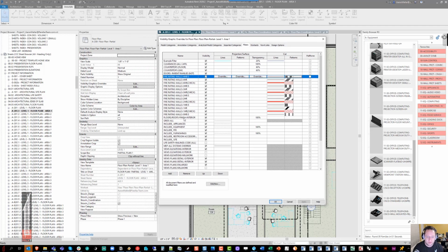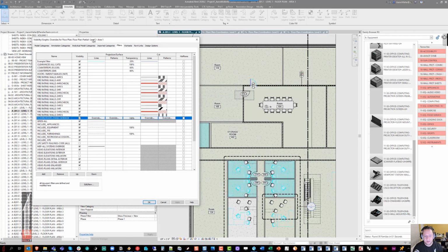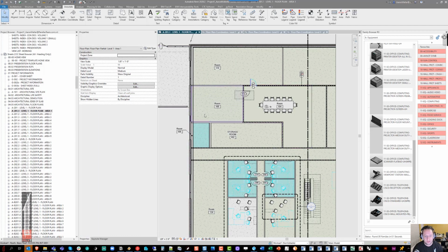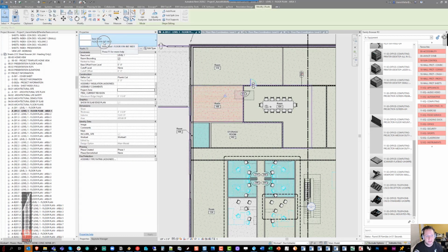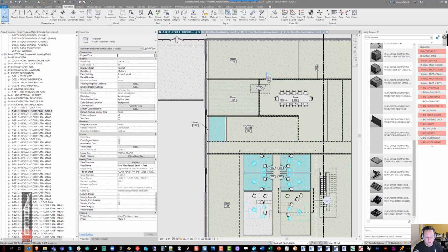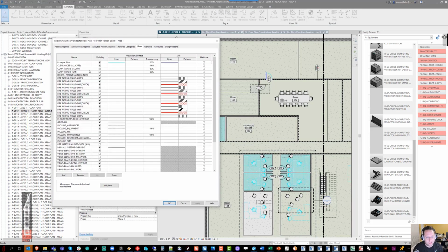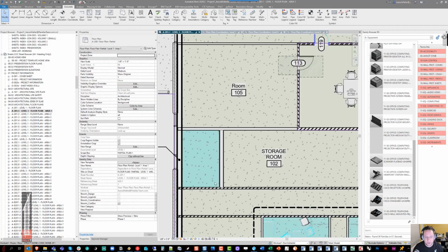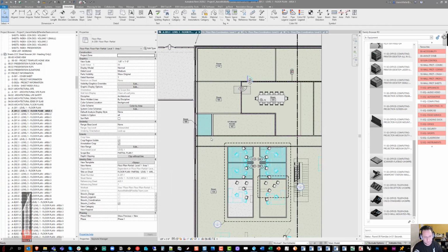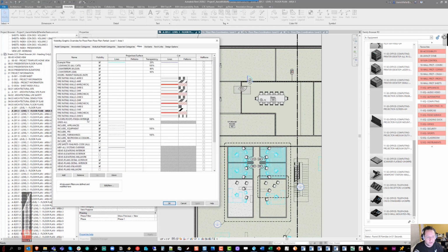Very important filter follows the fire rating, and that is floors and roofs finishes on the interior. This filter is looking for the letters FIN and INT in the name of both floors and roofs. Our 1/8 inch documentation floor plan typically won't show those finishes, as they'll show up on a finish plan. This filter is usually used to simply turn on or off those finishes, and you'll see here we just removed it from the view. If you have complex floor patterns, that one will make a lot of sense.